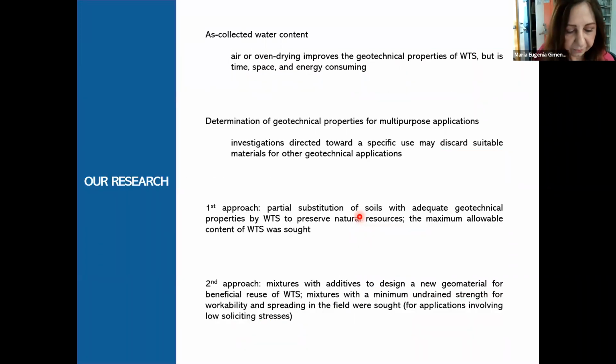Our research, what we want to bring here: we wanted to investigate the feasibility of employing WTS as collected, at its water content. We know the advantages of drying. Air or oven drying improves the geotechnical properties of soils, but it's time, space, and energy consuming. And we wanted to search solutions for developing countries and small municipalities as well.